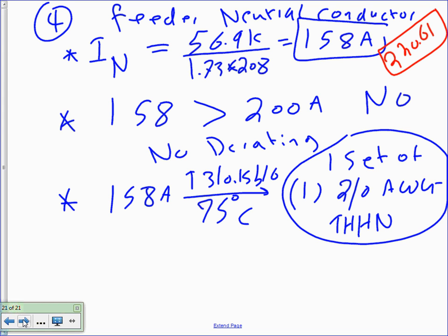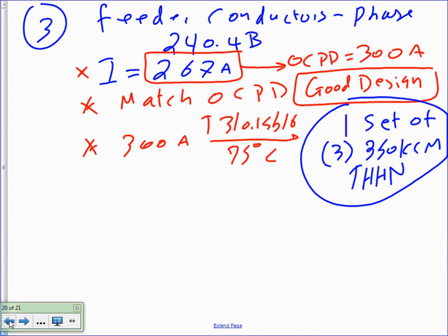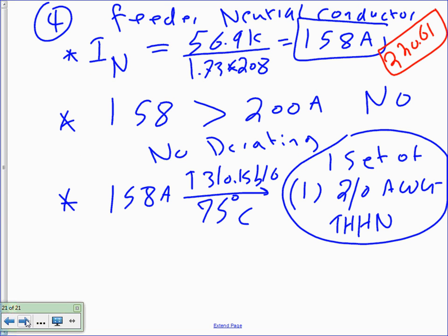My rule right now is right here. Okay. Any questions, guys, about my 2 AWG conductor for the 300 amp panel? So if you go work for somebody and they tell you we're going to pull a full neutral 350, are you violating the code? No. For safety, future, whatever reason, up to 300 is a good idea. Higher than that, not really. Okay, number 4 done.